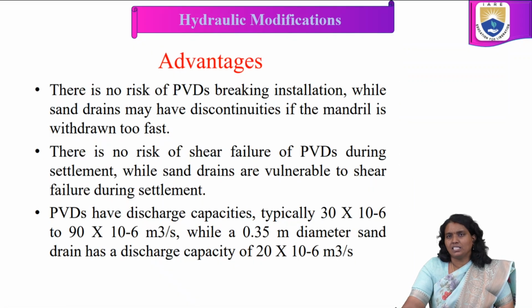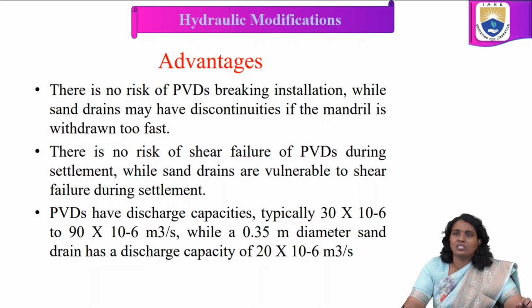Coming to the advantages of these wick drains, these prefabricated vertical drains which we use, there is no risk of PVDs breaking during installation, while sand drains may become discontinuous if the mandrel is withdrawn too fast.